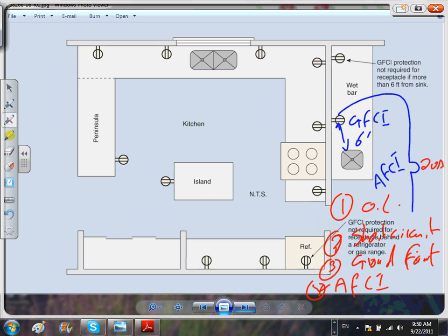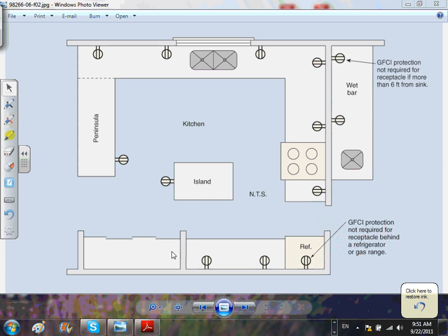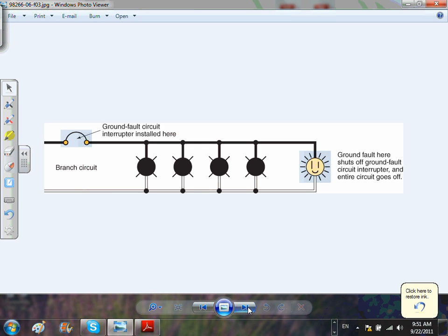Now I can add more functions. Chris, when I start doing medium voltage, the first thing I have to change in my mind is that a circuit breaker is a multi-function device. They call the overload one function. Each one of these is a function, meaning it's part of the circuit breaker. It could be designed, added to the circuit breaker, and utilized. Anyway, if it's in a basement, it has to be arc fault as well. Moving on, we talked about the ground fault circuit interrupter, guys.